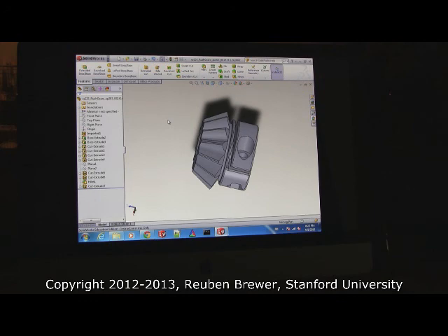What's the difference in the two? They both round the edges, right? No, a chamfer is a sharp angle. Okay, right. How many millimeters is the cut for your name? 0.5. Basically, the reason it's 0.5 is because if it's less than that, I won't be able to see it. And if it's bigger than that, it will hurt the structural integrity of your plastic. So, does everyone have your initials printed into your gear?